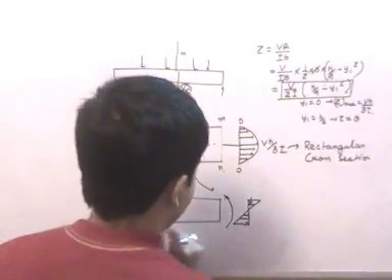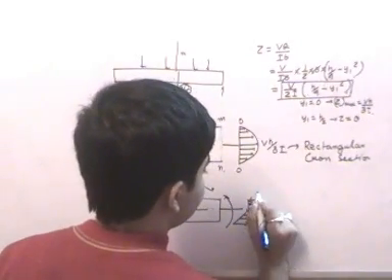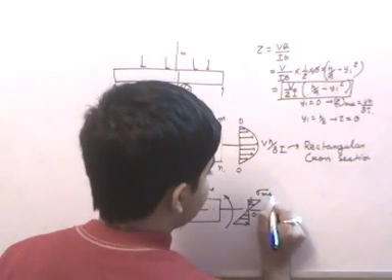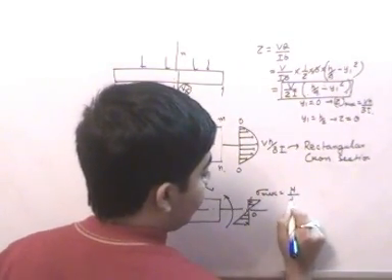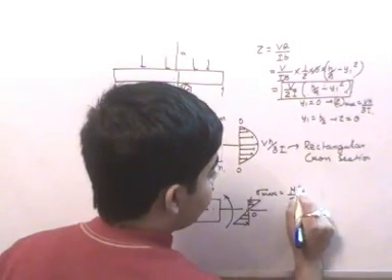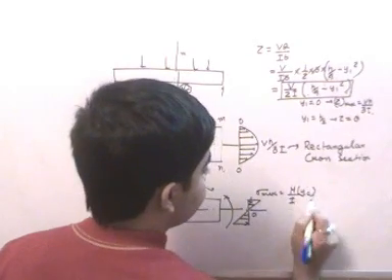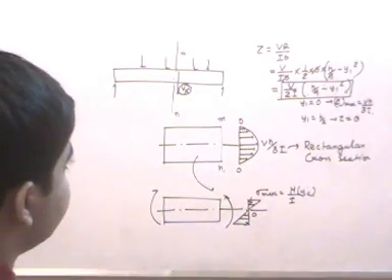Right. And here at the neutral axis, the normal stress is 0, and at the top it's equal to sigma max is equal to M by I into y, or I should write it yc. Right. So this is the brief summarization of